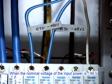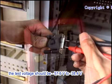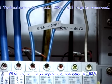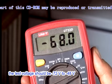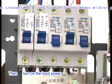When the nominal voltage of the input power is -48 V, the test voltage should be -57.6 to -38.4 V. When the nominal voltage of the input power is -60 V, the test voltage should be -72 to -48 V. Then turn on the input power.